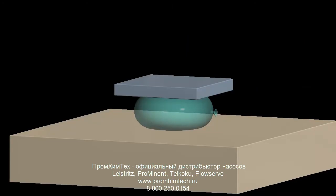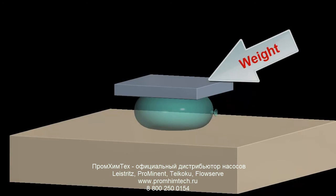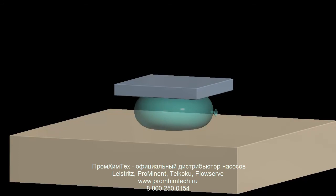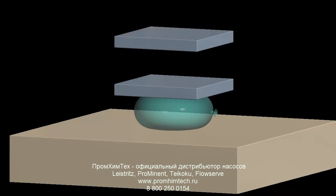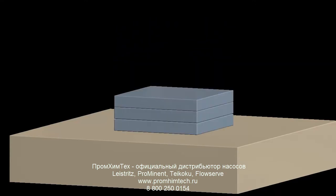Let's take a look at this short animation to help illustrate how this gas bubble collapse causes the damage that it does. In this animation, this plate represents a part that is being damaged by cavitation. The inflated balloon represents a gas bubble that is formed in the fluid, and this weight represents the fluid pressure that acts on the surface of the gas bubble. Notice that the balloon is able to support a certain amount of weight, but at some point the balloon is no longer able to support the increasing weight and eventually collapses under the load. And having lost its support, the weight crashes down on the surface of the part.